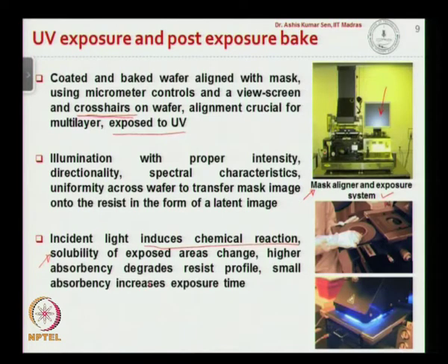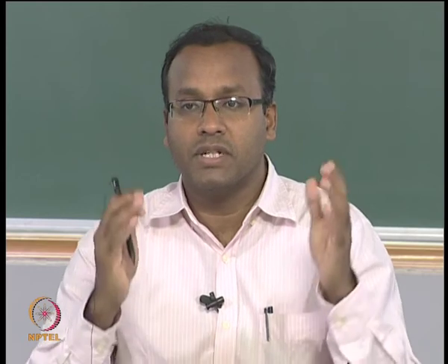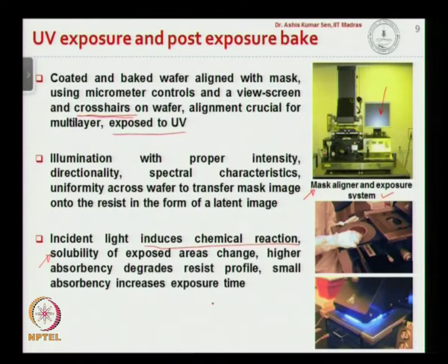If your beam comes straight, then because of the higher absorbency, it is going to penetrate more in the lateral direction into the photoresist. So if you want to achieve a flat profile, instead of a flat profile it may diverge in the lateral direction.